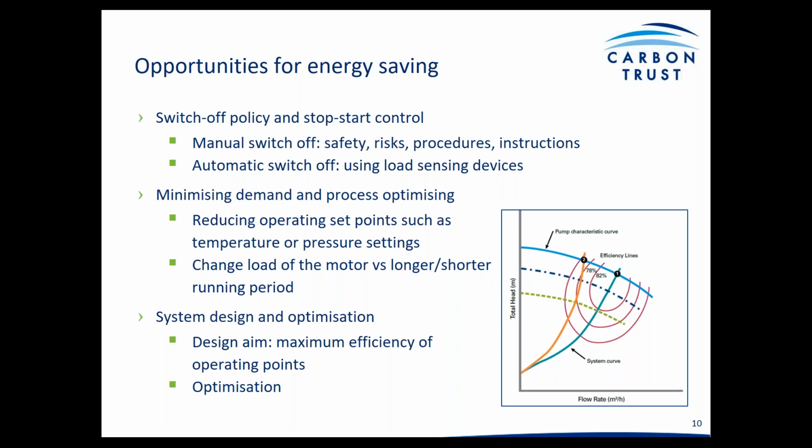This is particularly important on fan and pumping applications. As we can see in the picture, point 1 is running at a higher efficiency level than point 2, just by changing the operating setting of this pump.